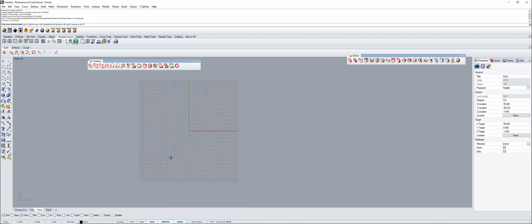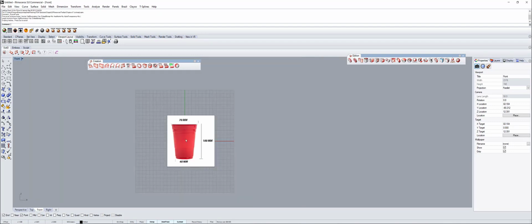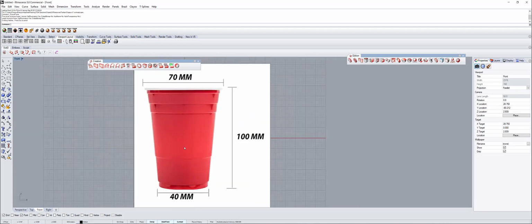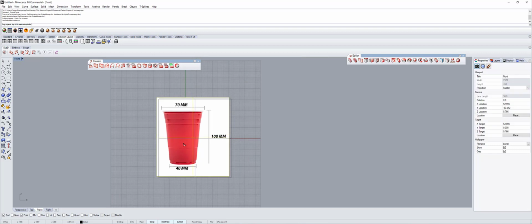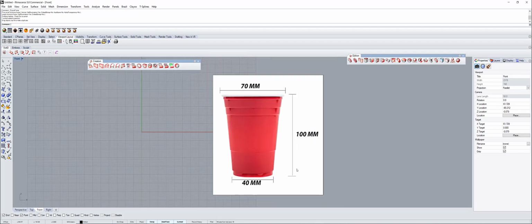So just click and press shift so it doesn't do these round turns. You press shift, it's gonna go straight to the right, and click to drop it. So here we are. Here we have the cup, just a simple cup. Yeah, this is a very simple tutorial. This template says that we got 100 millimeters high.